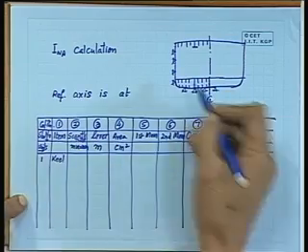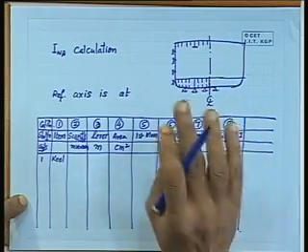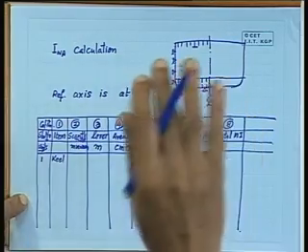We have seen the diagram and we see this structure here. We say that the neutral axis will be below the mid depth. Now, if for example we say that the depth of the vessel is say 9.5 meters and mid depth is 4.75 meter, we can consider that the assumed neutral axis is some round figure below 4.75, maybe 4.5 meters or 4 meters, but still we have to do a calculation.